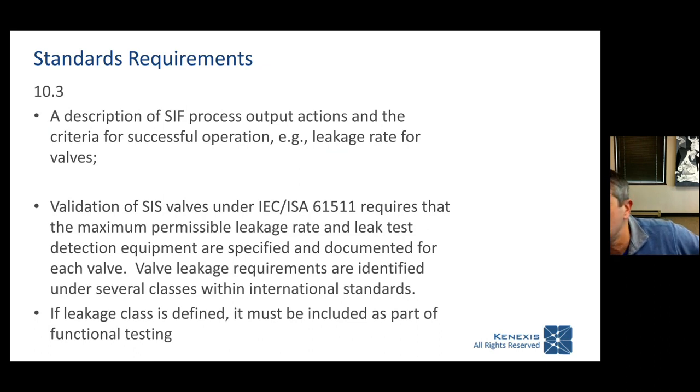But one of the things that you do need to document, one of the items on that bullet point list, is that you need to specify a description of SIF process output actions and the criteria for successful operation, exempli gratia, leakage rate for valves. So the example would be leakage rate for valves, but another item that is actually documented elsewhere is that the valve closure time requirements is another one of those performance standards that you're going to want to specify for a valve. Now, let's talk about this a little bit more.